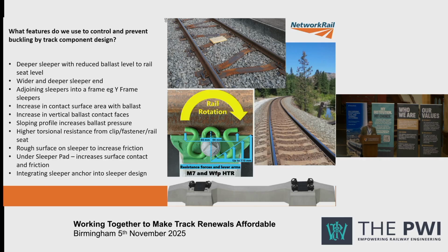You've got torsional stiffness in clips, so the Vossloh clip there provides additional torsional resistance via rail seat width, twisting, and making the ladder effect more rigid, so you don't get a more snaky effect in the track. So the torsional resistance of clips, again, is really important in sleeper design. And then there's increasing the friction, the contact surface, which undersleeper pads do as well, increasing all of the other surfaces for contact with ballast.